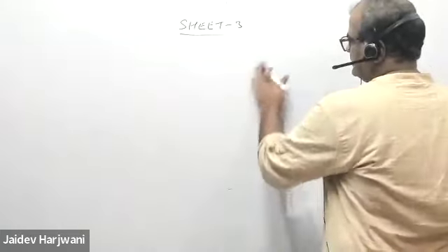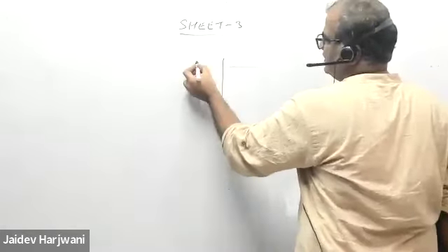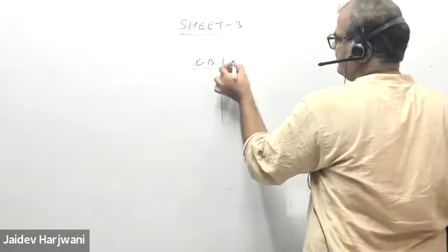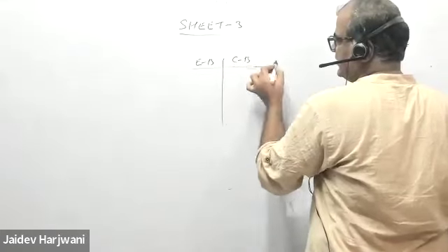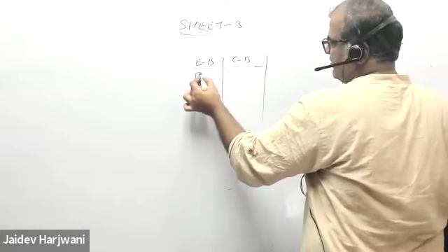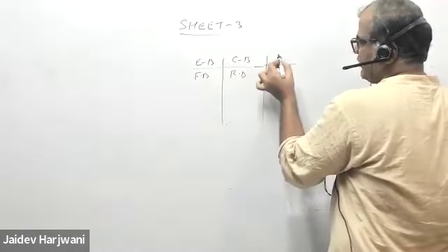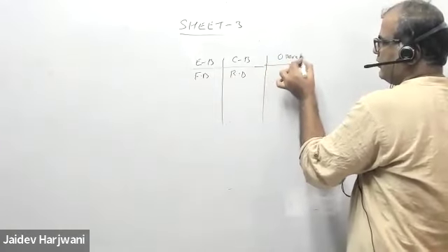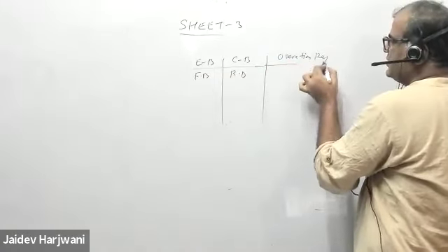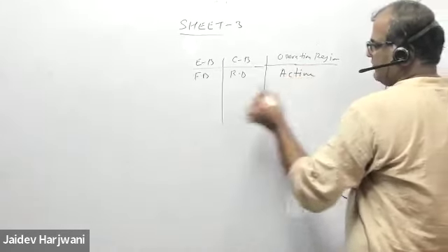Okay. So we have discussed in the class, say we have two junctions, the EB junction and the CB junction in an NPN transistor. If this is forward bias and this is reverse bias, then the operation region is active.